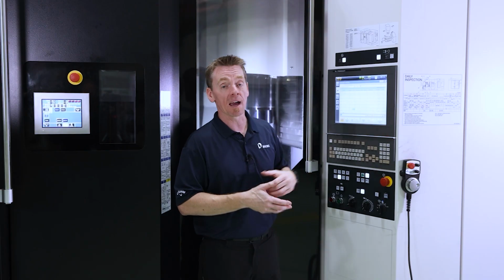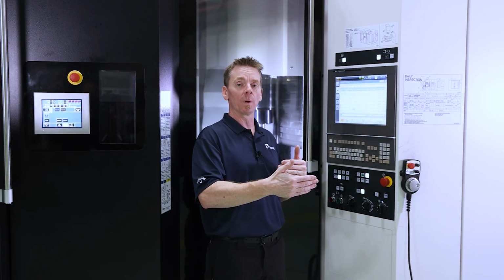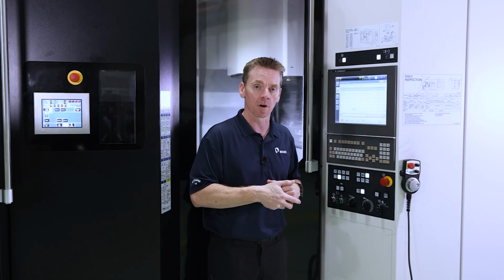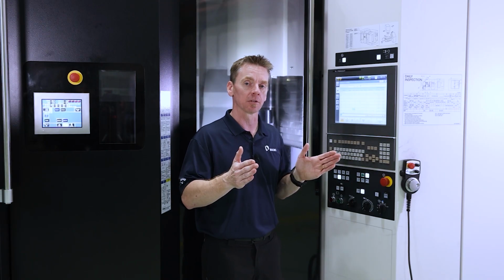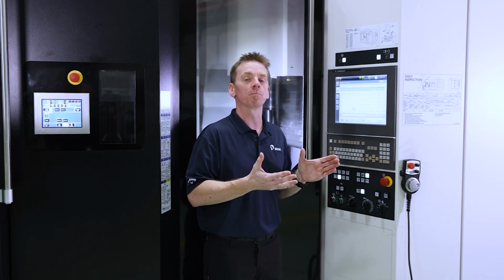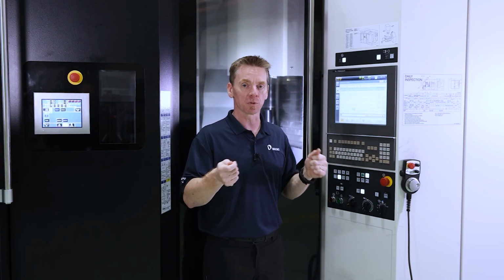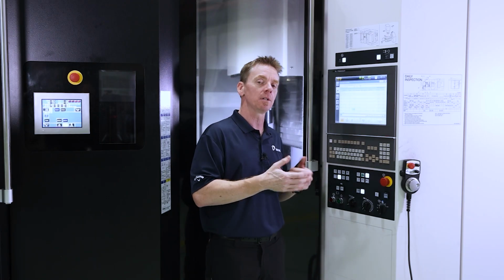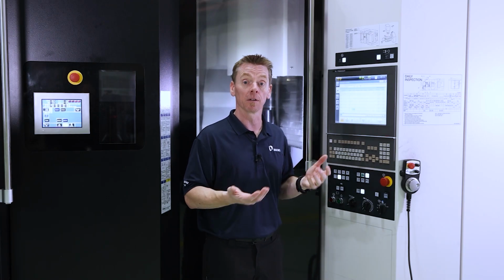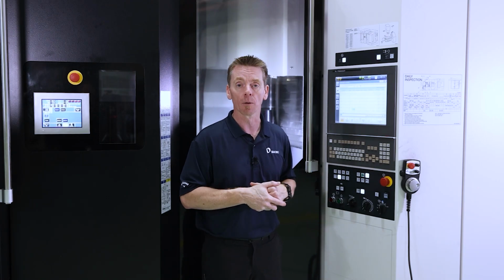Also on these machines, we have collision safeguard. If you're using level 2 collision safeguard, it is really great to have a master library that all your jobs can pull from. That way, if you need to switch tools at the machine, you're not redoing a collision safeguard project. You're literally changing the tool number, and away you go.